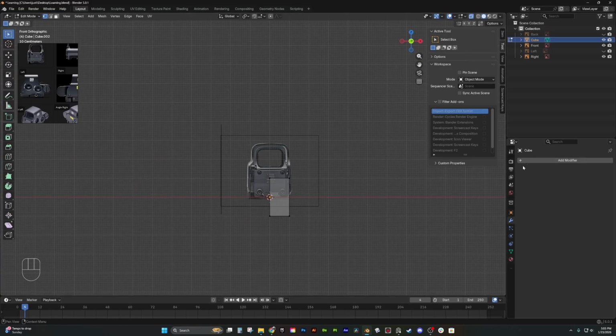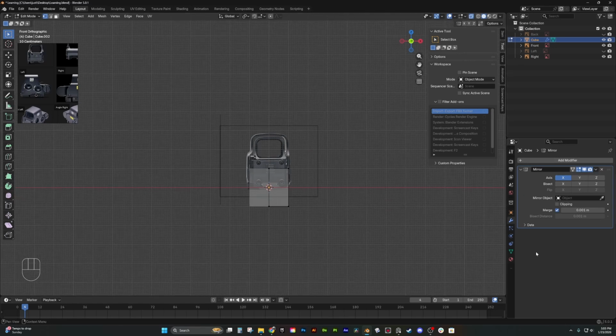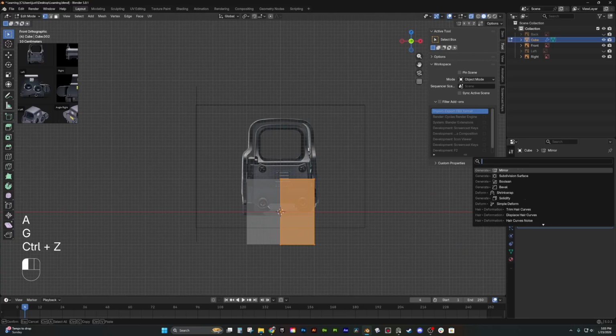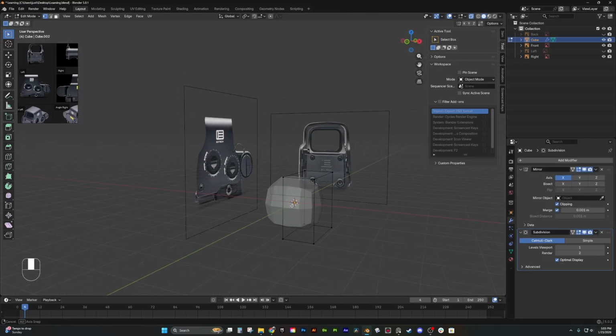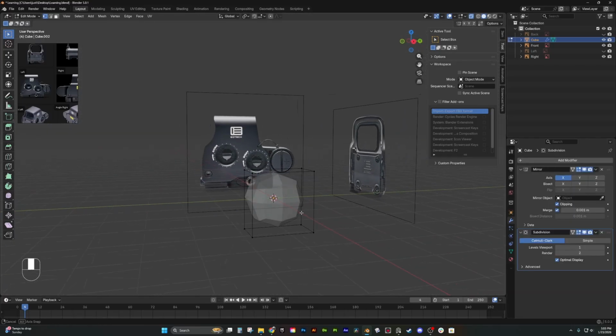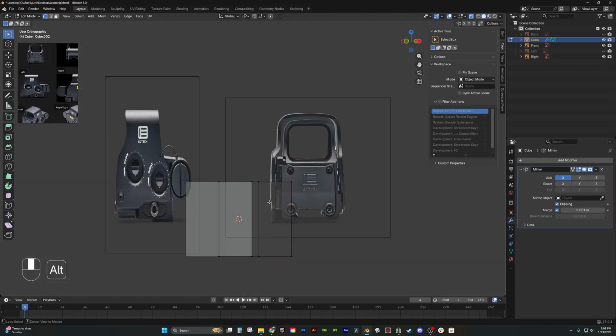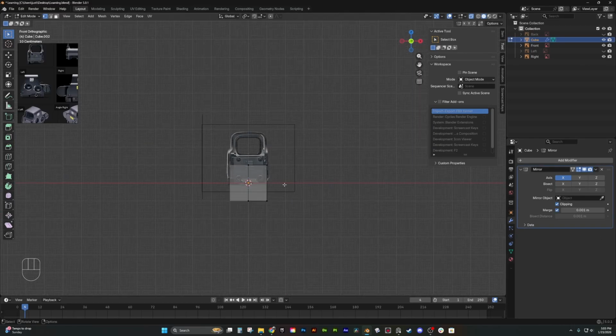And so the first thing I would want to add, unlike our last demo, is the mirror modifier. Later on, we'll add the subdivision surface modifier. In that last demo, I had the sub D go first, but it's really recommended to have the mirror go first. Then you can have clipping on. That way it always stays together, and then you could smooth it out with the subdivision surface modifier. We'll put this on in a little bit, but for now I want to get the basic proportions down, and we can decide what we want to model first.